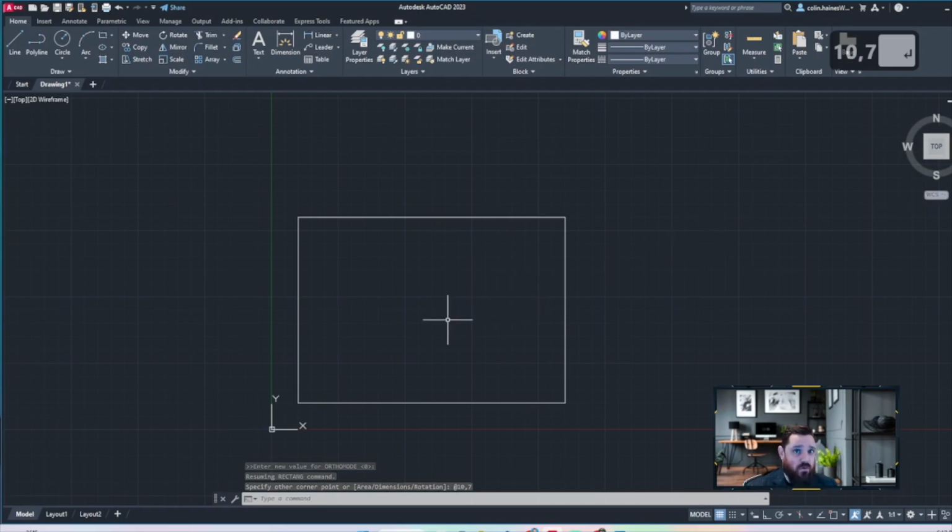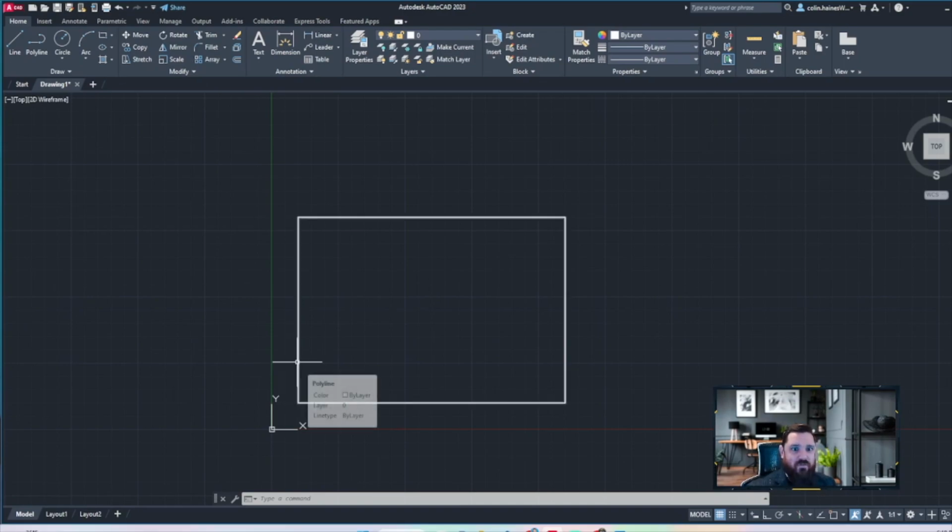So instead of going directly to the absolute coordinates of 11, 8, we got there by typing in the dimensions we wanted. Relative coordinates in the rectangle tool are infinitely more useful if you are not starting from a known point, or if you're starting from some weird point with some crazy decimal.